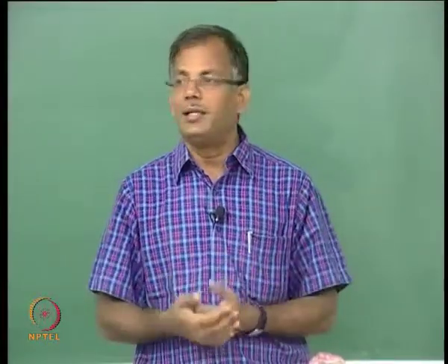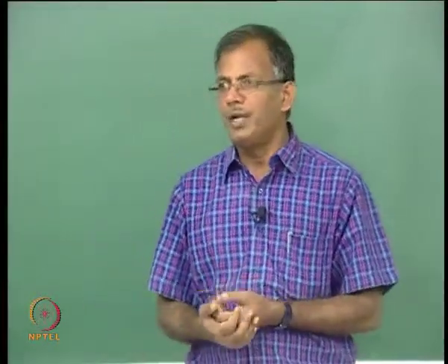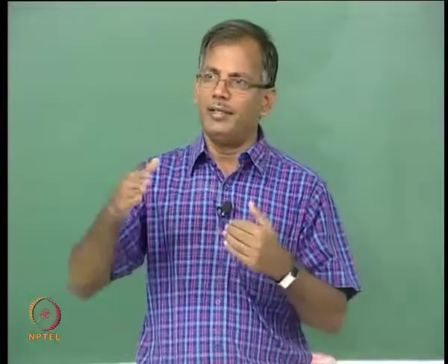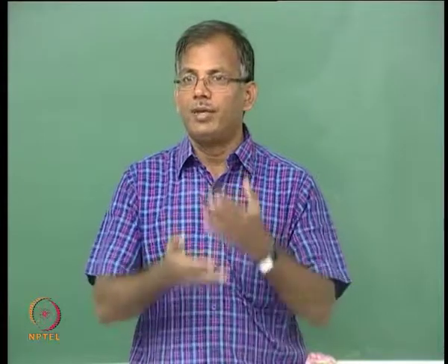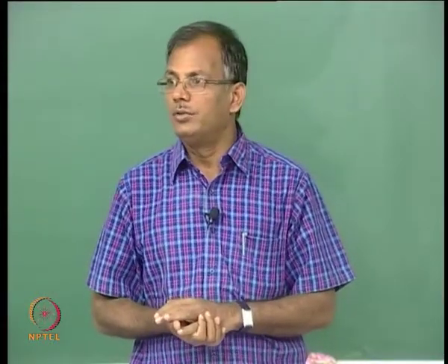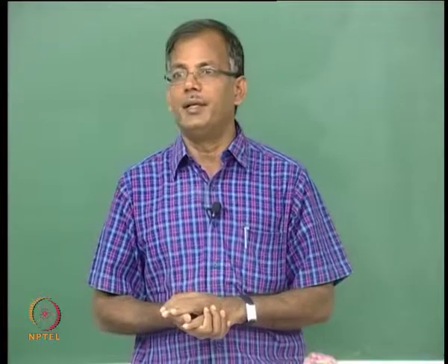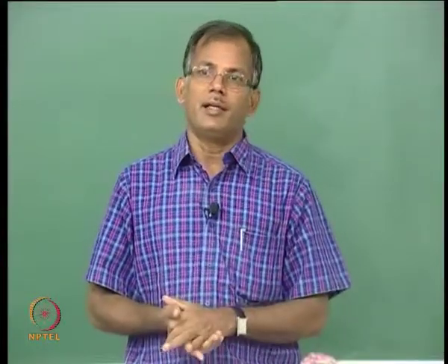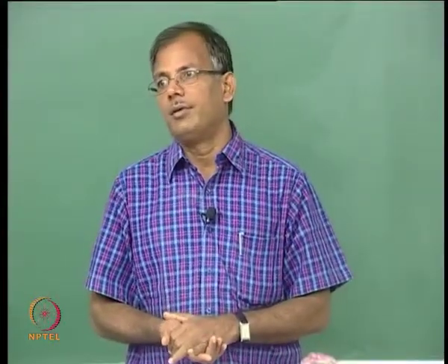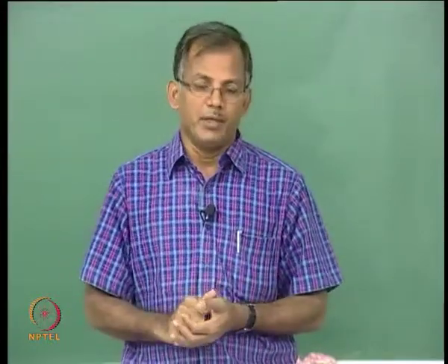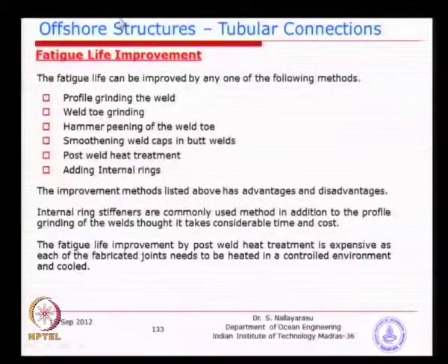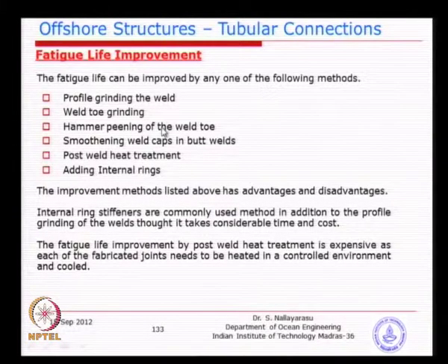Fatigue, changing material is not going to help, because you have only steel of a variety of yield strength changes. Unfortunately, fatigue is not at all related to the strength of the material; it is basically a material characteristic against cracks. So, even a change of material is not going to help. That is the time we need to start thinking of ideas other than just strength, which can help us increase the design fatigue life.